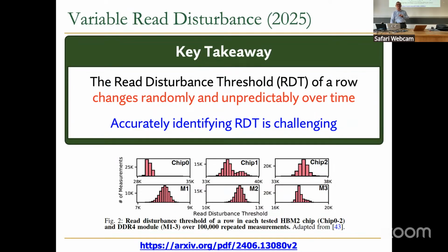Yeah, that's a very good question. Basically, there is certainly a RowHammer type of thing in NAND flash. It's not called RowHammer. We actually studied it earlier than RowHammer, and that's one of the reasons why we started looking at RowHammer. There are read disturbance mechanisms in NAND flash. Whenever you read a row in NAND flash memory, you apply some reference voltage to that row. But for all of the other rows in the same, I'll call it a subarray for now, you apply a much higher voltage to inhibit them from communicating their data to the bit line. And you actually cause a lot of disturbance because of that. So there is a very similar mechanism.